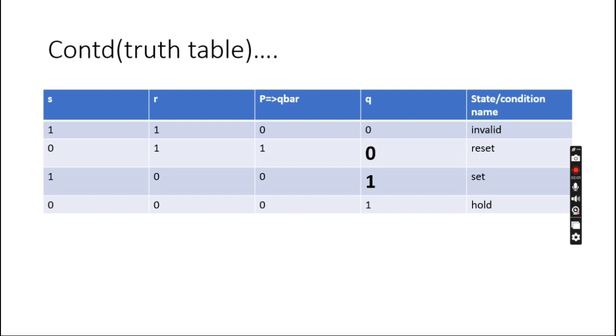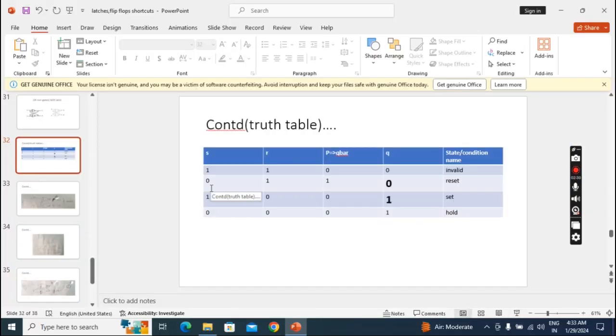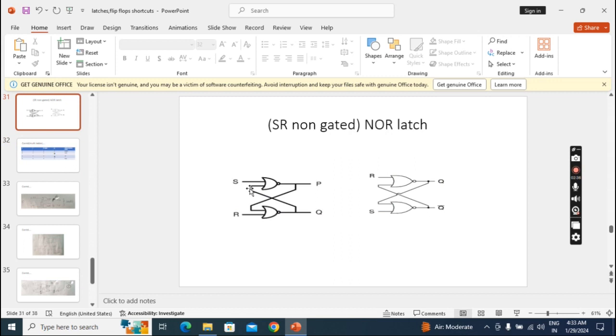Okay, so here in a NOR latch, if we keep this circuit in 1 1, when we apply input 1 1, it will be invalid. Okay, so whenever we want to make it useful, we have to change the input values. Okay, and one more reason, suppose initially if I apply 0 0 to the NOR latch, what will happen? We don't know the second input. Suppose here if I apply 0 0, I don't know the second input of each gate. Then I cannot predict the output.